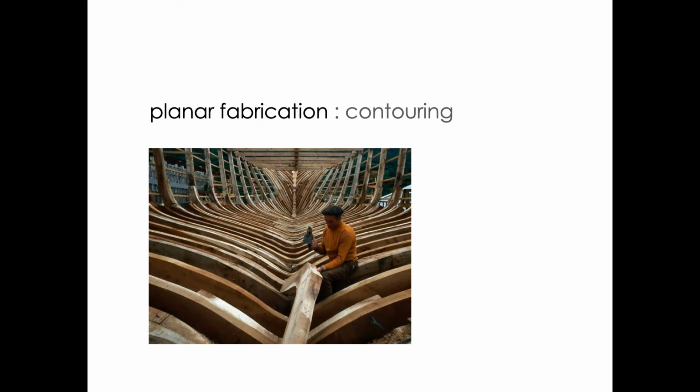This is a craftsperson working on the hull of a boat, right? So you can start to understand this wooden boat, this idea of contouring, right? So in Rhino, we have the tool called Lofting, which involves taking a bunch of sectional profiles like these structural ribs and then skinning in between them to create a surface. But in the boat or shipbuilding industry, lofting is actually the reverse process. It's taking a complex shape of, let's say, a boat hull, and then beginning to delineate and mark out those sectional cross sections for the componentry for, let's say, these ribs. It looks very skeletal, of course,